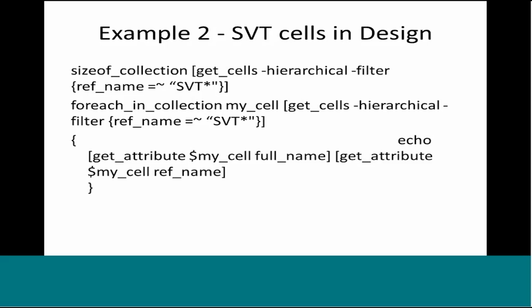The idea is that attributes will help us in writing powerful PrimeTime procedures. Even Design Compiler supports attributes. Some attributes may be different between Design Compiler and PrimeTime for some objects, because the aim of these two tools is different, but you can use it nonetheless.